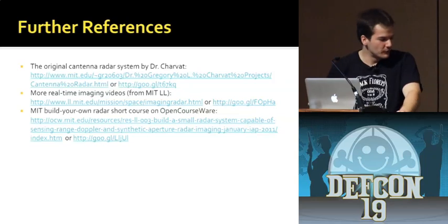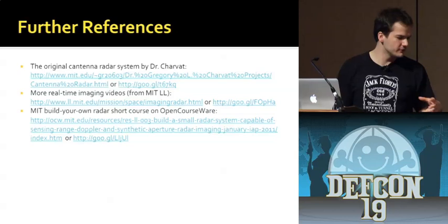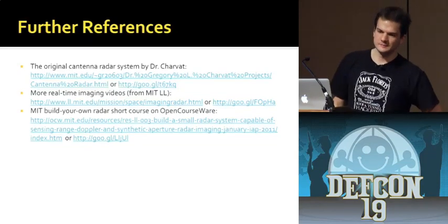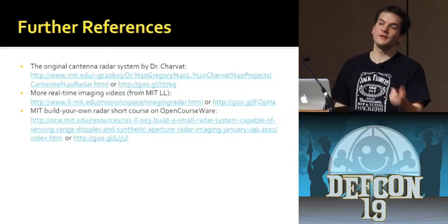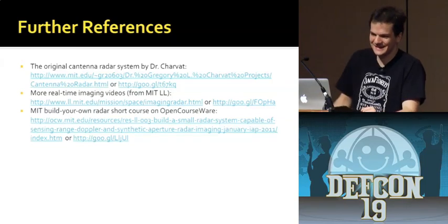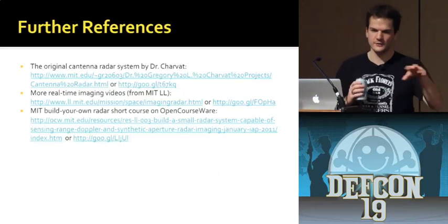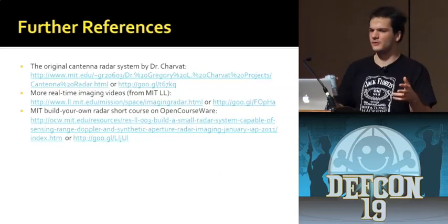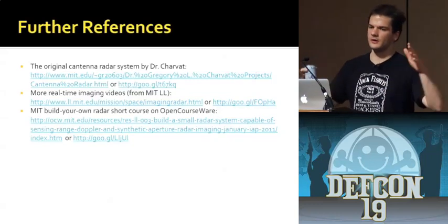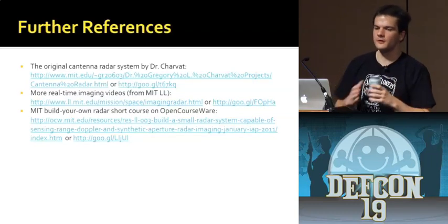Okay, yeah. To some extent, for the SAR stuff, we want something a little less directional than that. Part of it is that the coffee cans were what was available at the time. So MIT students drink more coffee? Well, that's probably true. Yes, we could graph that. But yeah, it's pretty open. You basically get different characteristics. If you're trying to do the SAR imaging, having a wide beam width is actually somewhat useful. It decreases some of your spatial fidelity, but you also get a wider image. If you have a very narrow beam, you're not going to get any signal from something that's further apart. So it's a trade-off there.